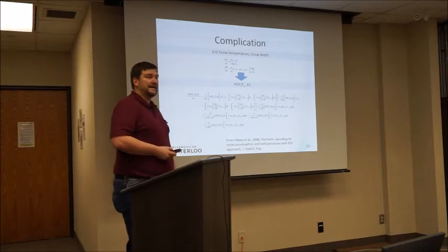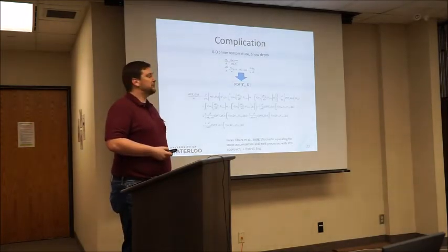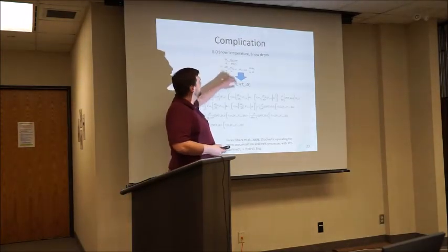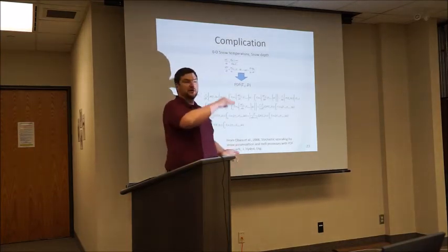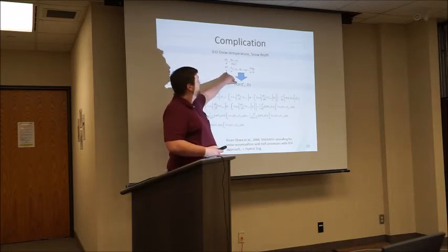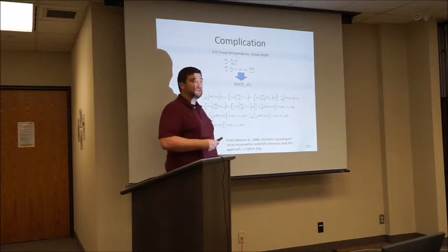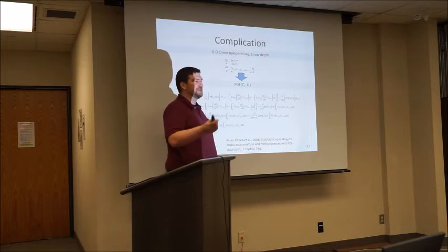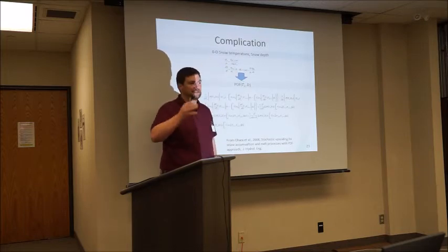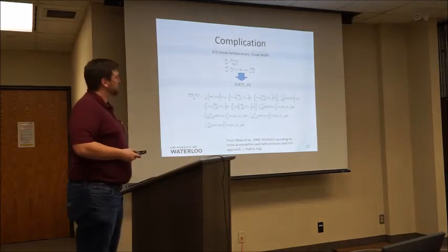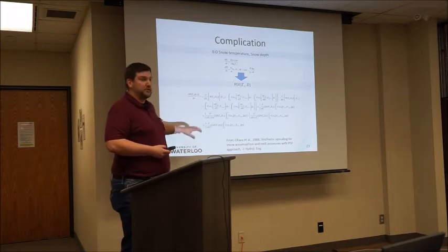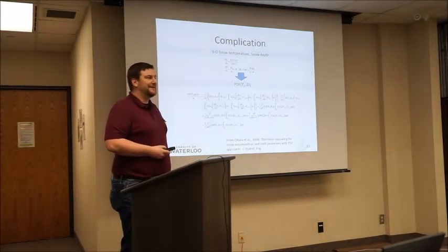So here's an example. Here's two ordinary differential equations describing temperature of snowpack and depth of snowpack at a single point. This is one formulation, and for a single layer snowpack, we can solve these no problem. Let's solve it for a heterogeneous domain with heterogeneous radiation where there are correlations and covariances that we have to track through between temperature and depth and consolidation and some dependence here on density and whatnot. And you do this once, the right way, and look at what we get.